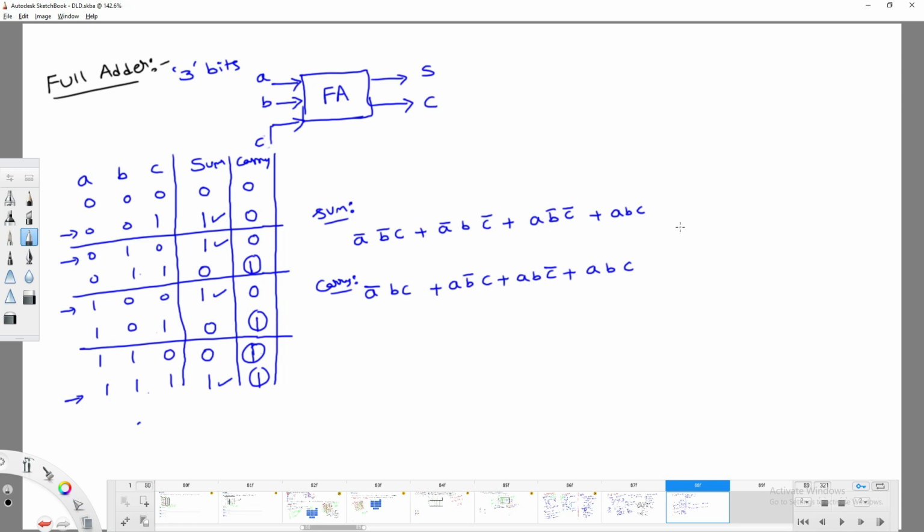So we are going to have the inputs A, B and C. Basically, you can construct it with the help of 2 input AND gates if required, or 3 input AND gates if required, depending upon the requirement or the question. Because this is in the form of AND-OR gates, once it is in this form, you can also construct it using NAND gates. Okay, fine.